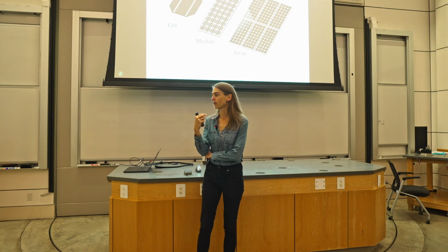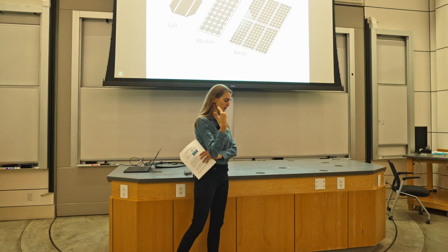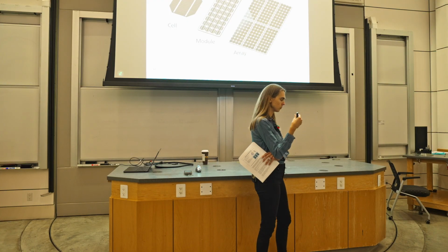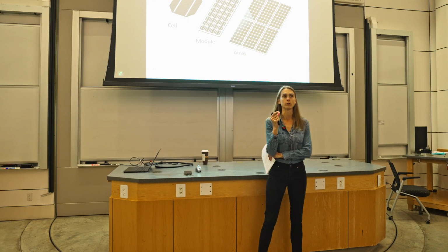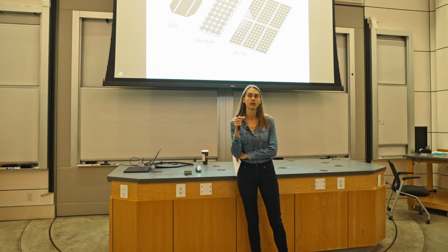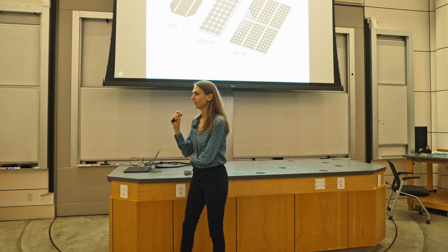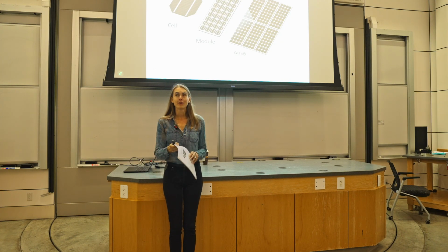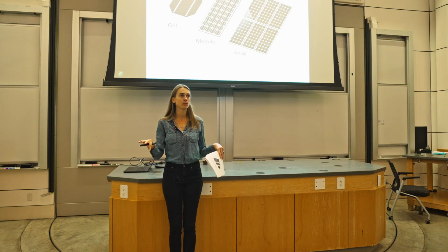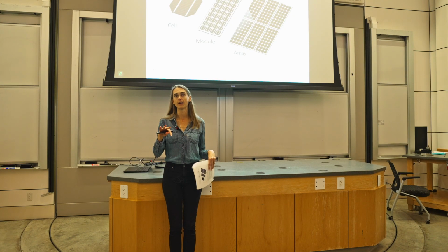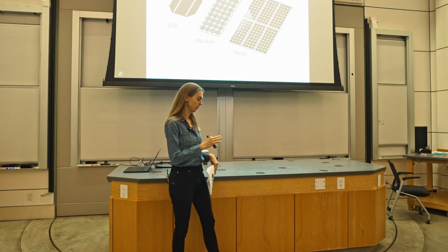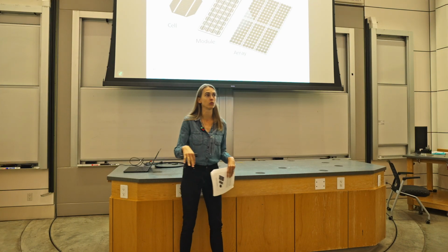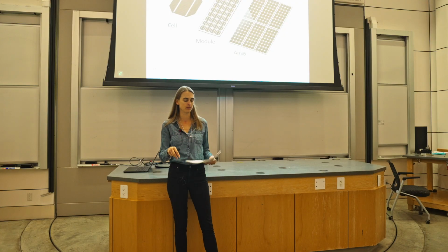So this is one of the things that we actually do at the Nevada Clean Energy Fund. If we're funding or supporting a solar project, we make sure that the contractor has done a shading assessment at the site so that they're not putting solar panels in an area that gets shaded. And it's also relevant when you're thinking about utility scale projects. If you don't space your panels away from each other enough, they could shade each other at one point during the day. Or if your land isn't flat, that could create additional shading dynamics between your panels.